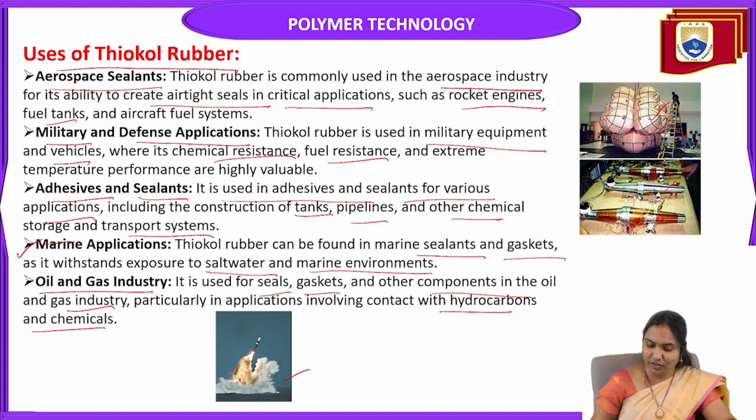So in this session, we learned about what natural rubber is, what the drawbacks of natural rubber are, and the processing of natural rubber: what steps are involved, how we harvest latex from the trees and then transform it into usable rubber products. We also discussed synthetic rubber, including the synthesis, preparation, properties, and uses of Buna and Thiokol rubber.